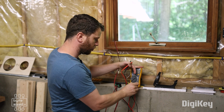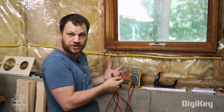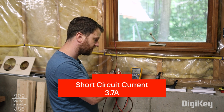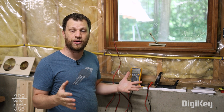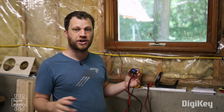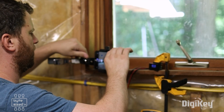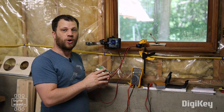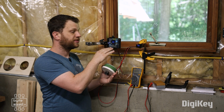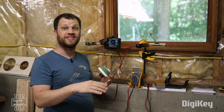To measure current, I need to switch over to current mode. And I'm going to short out the circuit using the multimeter and measure the current. My short circuit current right now is 3.7 amps. So far, we haven't pulled any power out of the solar panel. So to do that, we need to hook up a load. And to make things a whole lot easier, I've installed a little electric energy meter in series with the panel. This is going to tell me the voltage and the current at any given point. Once I connect up this load, I want to sweep it across its whole range and collect all of the data points so that I can put them into a spreadsheet. My goal is to be able to plot the points so that we can see the power curve.